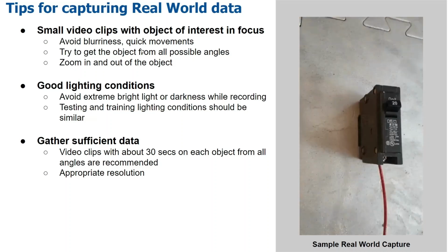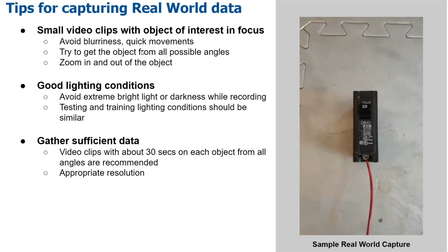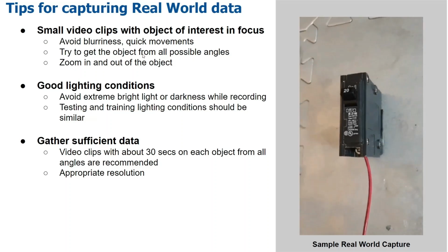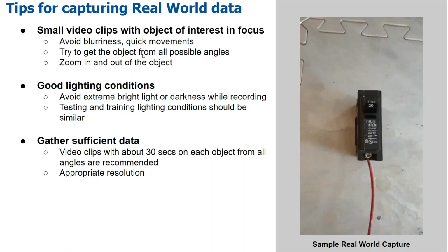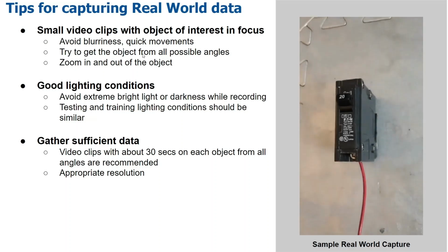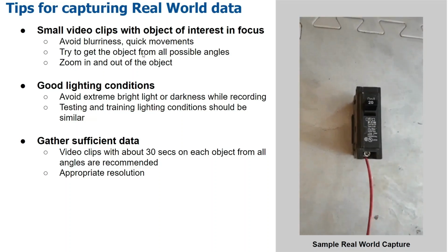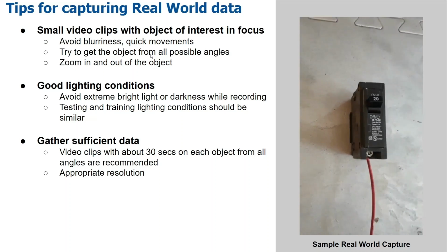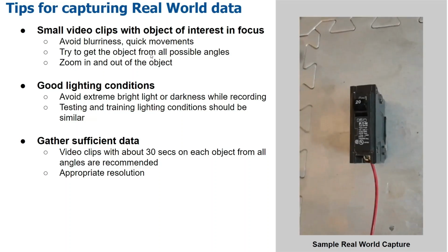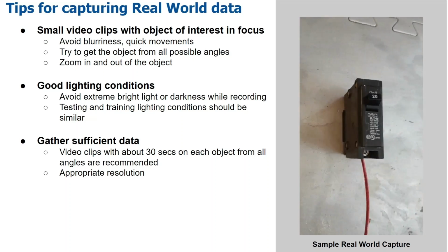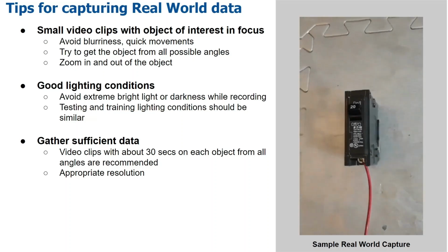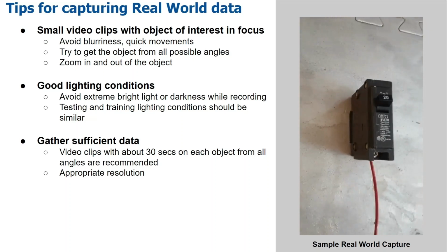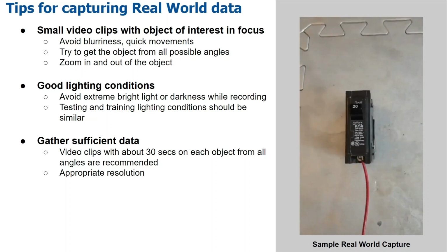Make sure the resolution at which you're capturing your data matches what you will input into your object detection models. For example, our object detection model, the DetectNet v2, would expect input in 640 by 368. So it was in our best interest to capture data in a resolution of the same aspect ratio, or keep it as close as possible to minimize image resizing requirements.